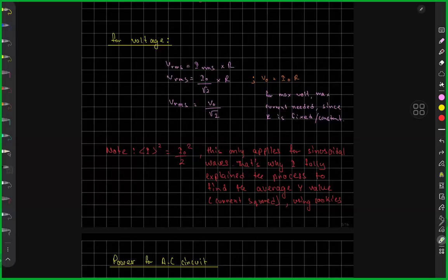Now the same thing applies to voltage. If the current is varying, voltage also varies, as I showed you, in the same proportion. So what is VRMS, or voltage root mean square value? I want to find the VRMS, so what do I include in my equation? It should be current times R, which is the normal equation. Does resistance vary? Not at all. Resistance is the same regardless of whether it's alternating current or direct current. But for current, I can have a different value in an AC supply and in a DC supply.